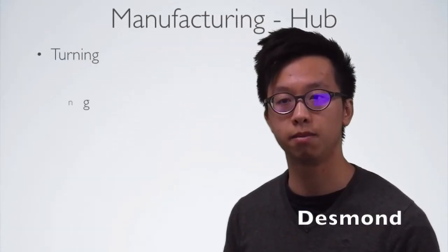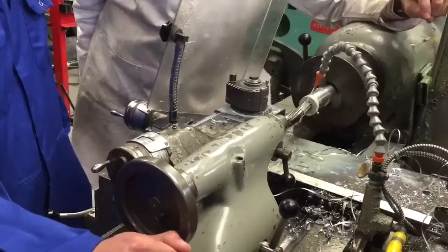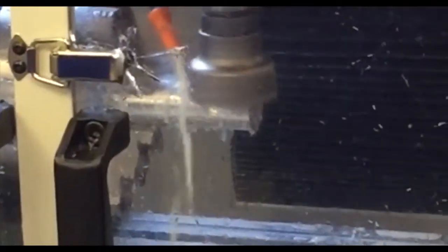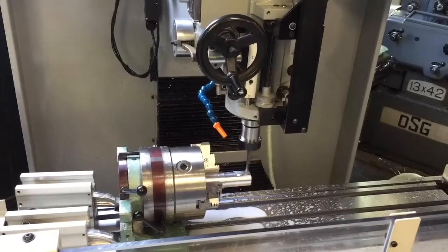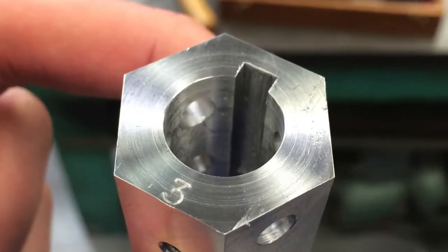The hub was manufactured via 3 processes: turning, milling, and broaching. Utilizing a lathe, the block of cylindrical aluminium was trimmed down. Then a hole was drilled in the center of the block using a tailstock. With a vertical milling machine, the cylinder was cut into the desired hexagonal shape. We then drilled the holes for minimizing mass onto the corresponding surfaces according to the coordinates entered. Finally, the keyway was produced by broaching.